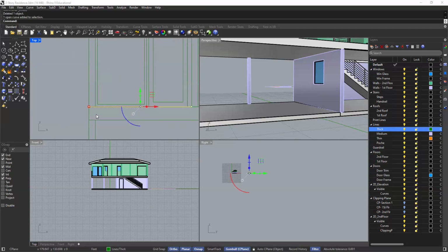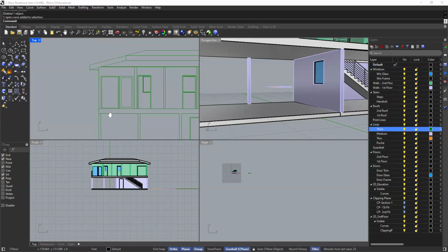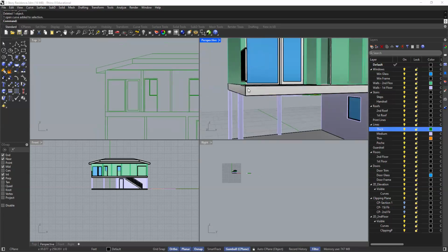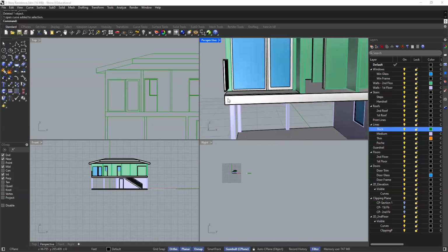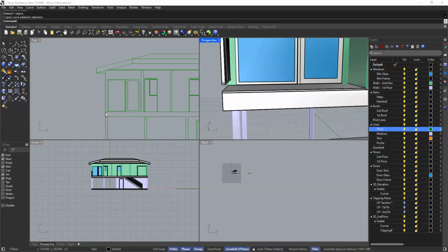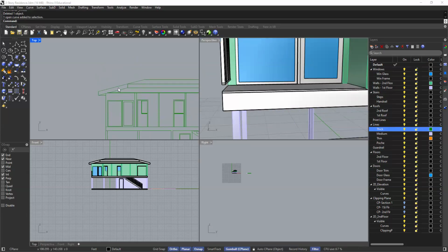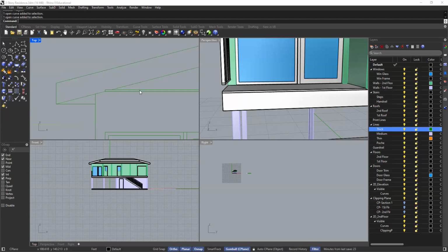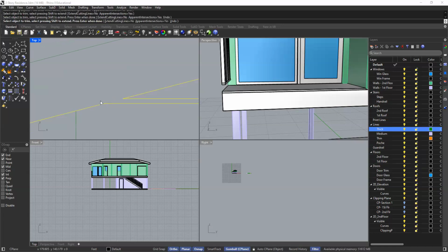Now with this one here, let's take a look. What are we cutting through? Yeah, so we're not cutting through anything here. So this will just end just like that. And then over here, what I'll want to do is have this little ceiling poche. So I'm going to use my trim command and hit enter, then click and click.